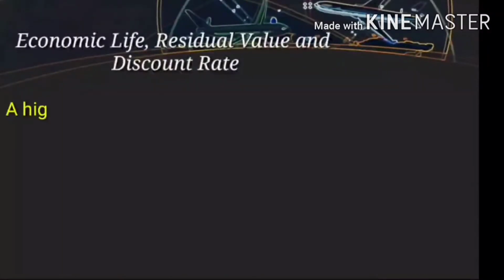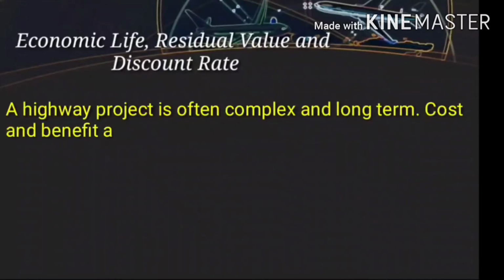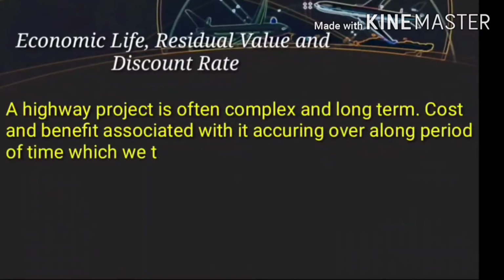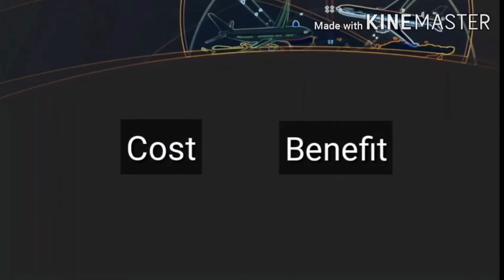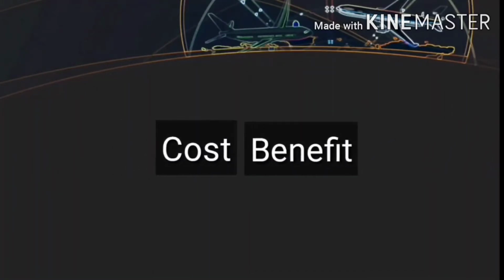A highway project is often complex and long-term, with costs and benefits associated with it occurring over a long period of time, which we term the life of the project. It is usually 20, 25, 35, and even 50 years or more. The costs and benefits occur at different times over this time horizon. Hence, they cannot be directly combined until they are reduced to a common time frame. This is achieved using a discount rate, which translates all costs and benefits to time-equivalent values.